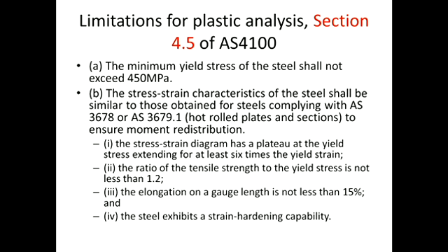So last week we looked at stress strain curve relationships as we increase the load. So one of the limitations for plastic analysis and design is that we have to have a stress diagram which has a plateau at yield. So this is what we saw last week.